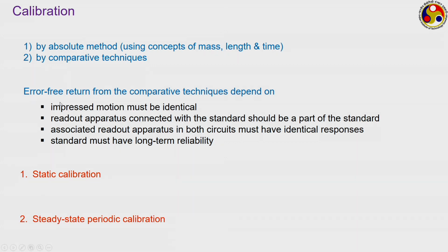In the case of static calibration, we can have two kinds of methods. One is plus minus 1 G turnover. That is a very simple situation where particularly low range accelerometers are calibrated in this way, where we just rotate the accelerometer upside down. Like if your accelerometer is like this, we just rotate it upside down, then how much is the change in the effective gravitational acceleration?